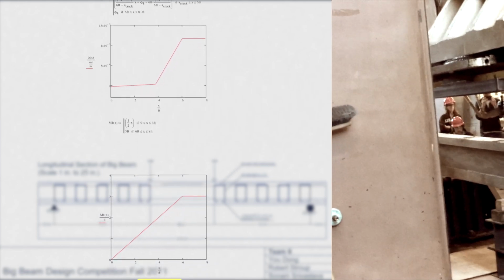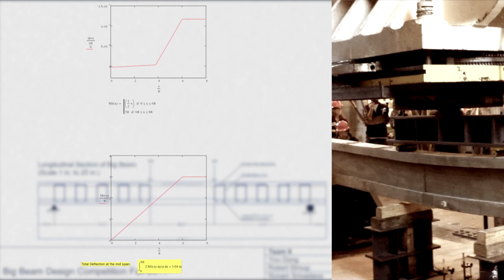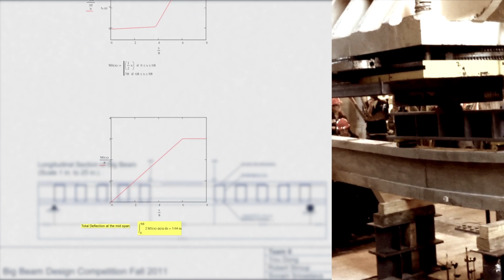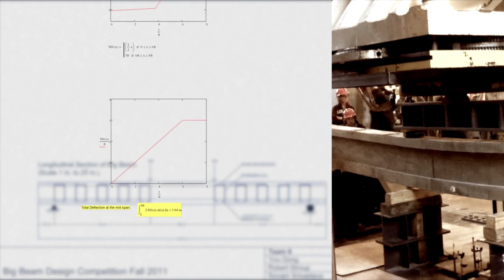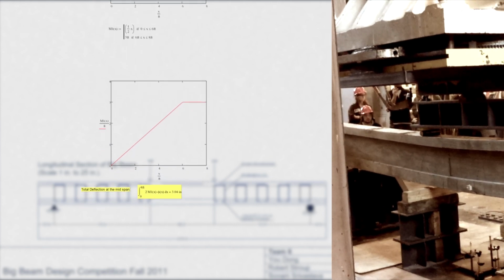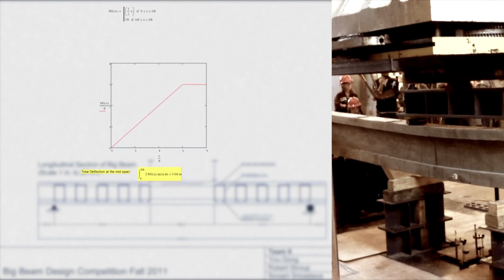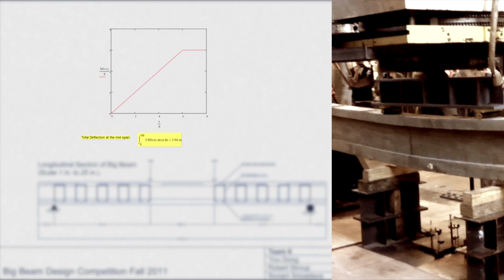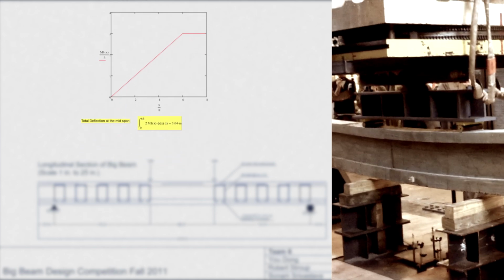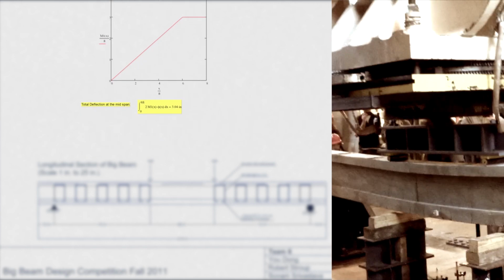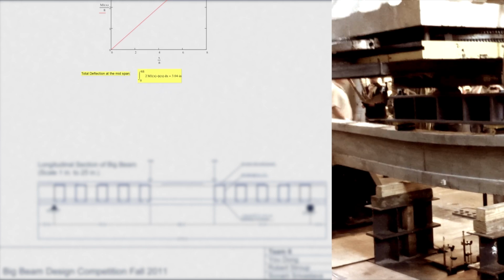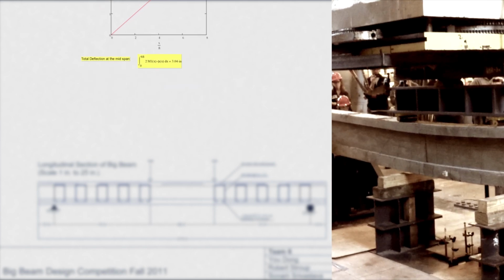By using ACI equation 11.5, we projected the curvilinear trajectory of the shear force with respect to the distance from the support. After graphing both shear demand and resistance, we then calculated the necessary shear reinforcement spacing. We determined that the maximum spacing for reinforcement was 12.75 inches. Based on the plot we formed, we determined that implementing number 3 bars at a spacing of 8 inches for the 6 feet from the support until the point of application would be acceptable.